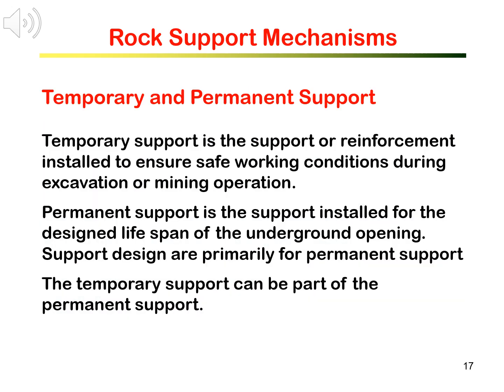Rock support in underground excavation is differentiated by temporary support and permanent support. Temporary support is the rock support or reinforcement installed to ensure safe working conditions during excavation or mining operation. Permanent support is the rock support designed and installed for the designed lifespan of the underground opening. For civil engineering tunnels and caverns, typically their designed lifespan is 100 years. So the support is meant to be functioning for that period or longer.